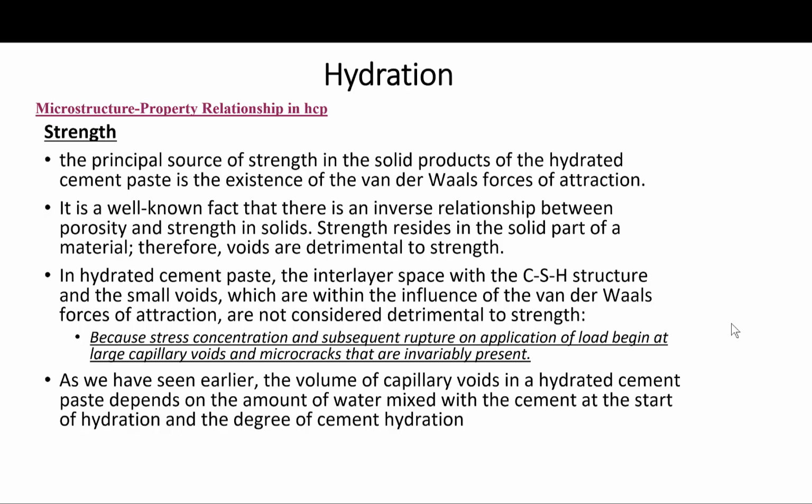First, let's look at the strength. It should be noted that the principal source of strength in the solid products of the hydrated cement paste is the existence of the van der Waals forces of attraction. Adhesion between the two solid surfaces can be attributed to these physical forces, the degree of the adhesive action being dependent on the extent and the nature of the surfaces involved.